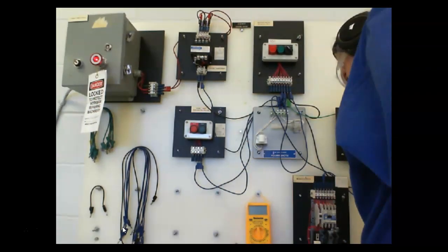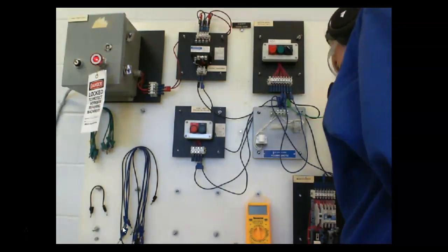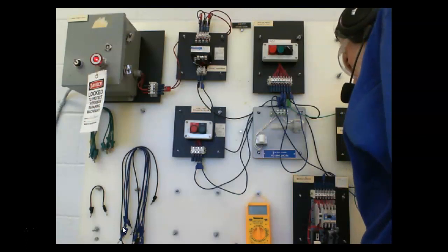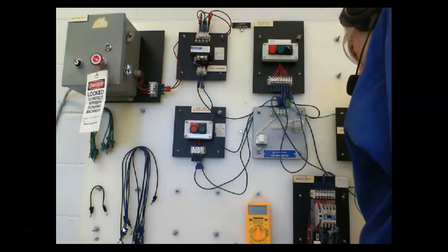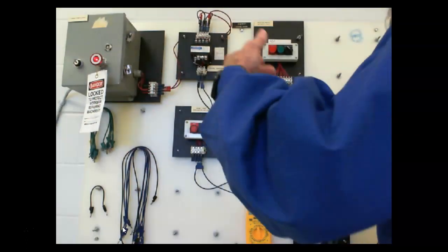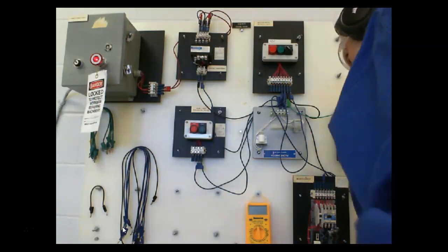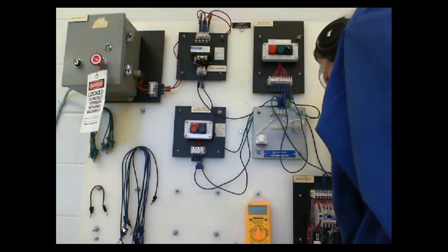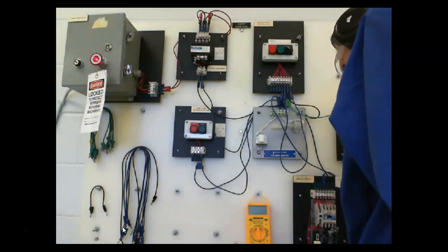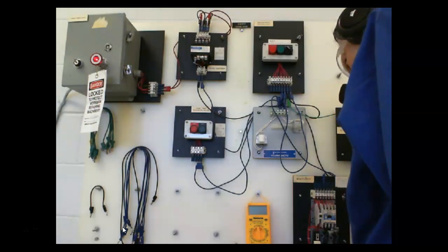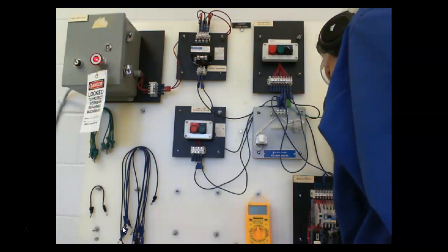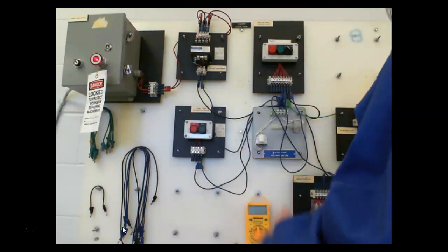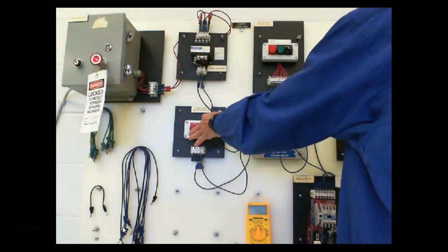Okay. So number 9 says place the selector switch in the hand position. Did the motor start? So that's A-9 right there. So y'all need an answer there. Press and hold the push button down. The motor should have started. If not, ask the instructor if you can use a digital meter. So ours worked okay right there.